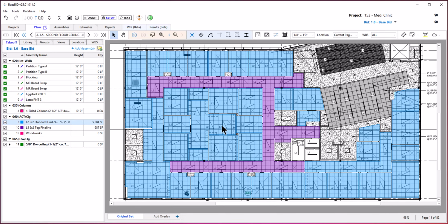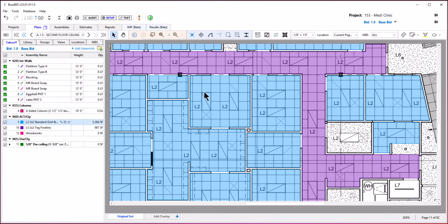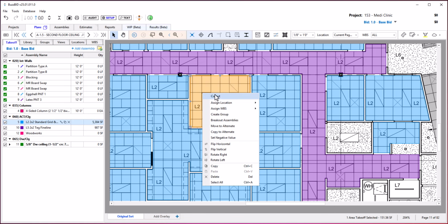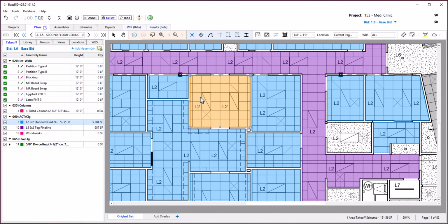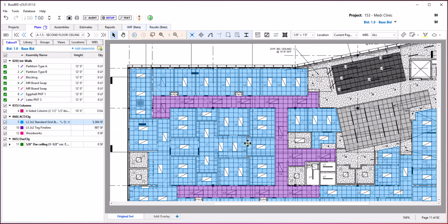If you want to back out your light fixtures, when you right mouse click on any area object, you get the cutout option. Here I'll drag and it should go through and count the light fixtures like this. The thing that's important to remember is I always need you to take a visual sweep to see if you agree it caught everything. In this case, I have one light fixture that got away from me, so I need to go add that manually.